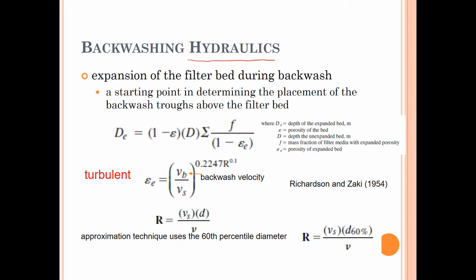As you remember, when we continue to do filtration, say this is a filter with grain, this bed, after some time the contamination, the suspended solid and colloidal particles clog the filter, and then the hydraulic head or head loss increases. Then we have to stop the filtration and clean that filter using backwashing. And we do backwashing by changing the direction of flow upward.